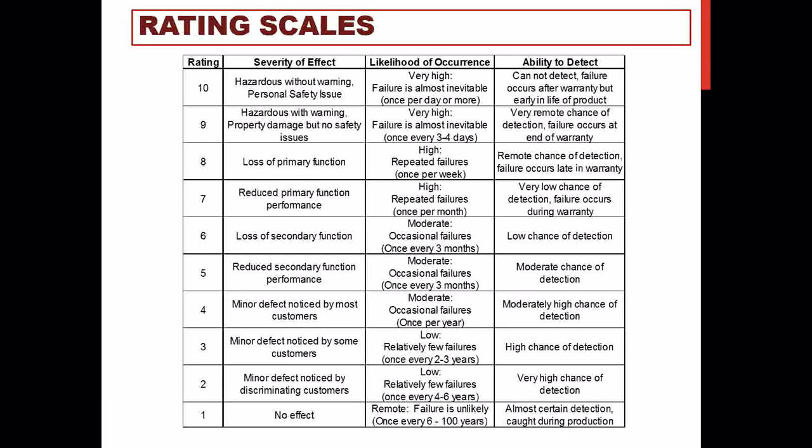And the key question I get asked all the time is what level of number would cause us to definitely want to look at the problem. And in general, that number would be about 120. So anytime you're over 100, you definitely want to take a look at it. But I would also say that if you have anything that has a severity ranking of 10, you definitely have to look at that too, and maybe even some 9s.